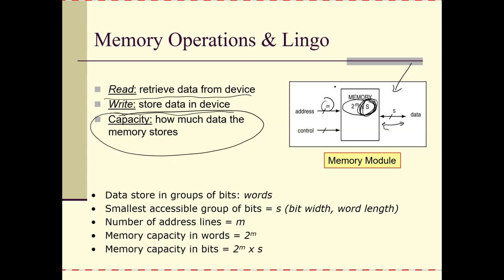Now this is going to be a classic binary thing here, where the chunks that this memory can hold is determined by the width of this data signal. So essentially, it's going to take those data lines. If, for example, there's 8 data lines, that means I can have 256 different unique values for an 8-bit number, and so that would be a memory that can hold 256 chunks, where all the chunks are 8 bits wide.